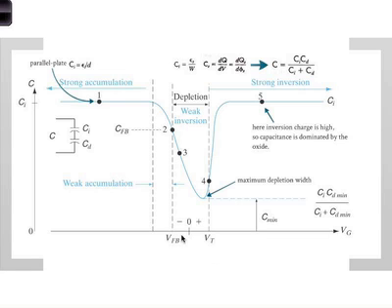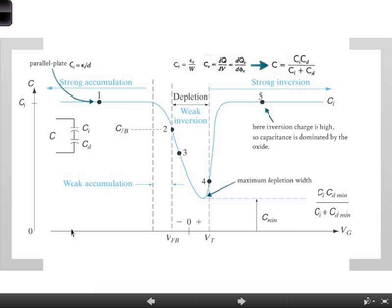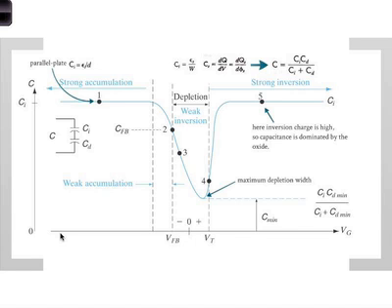Now this is again a P-type substrate, which means that the channel is N-type, and the applied gate voltage for proper operation has to be positive. You attract the electrons to create the channel. So let's start with the negative gate voltage. When you have negative gate voltage, we had accumulation last time. The physics was that when you apply negative gate voltage, you attract the holes, so you attract majority carriers. They're always conducting, so remember, we lose control of the gate. It's just like a resistor, essentially.